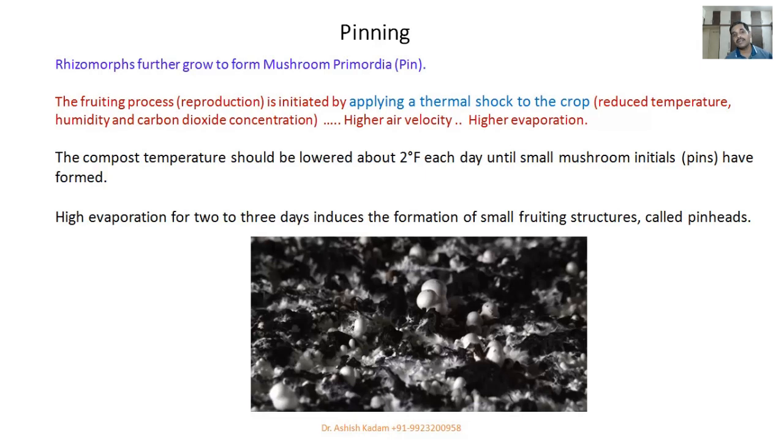Have you seen people measuring air velocity in the growing rooms? I have not seen. People are not controlling these parameters. They are putting small DX type AHU, which is not the right solution for the cultivation of the button mushroom, but people are using this technology without understanding the problems with it.